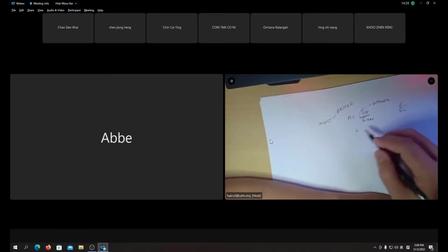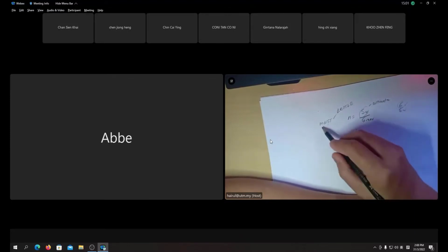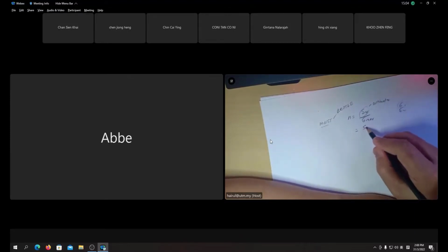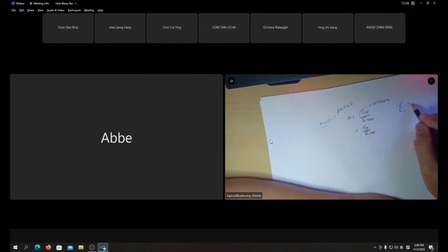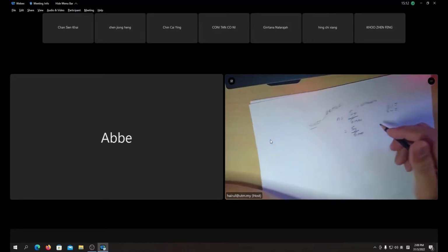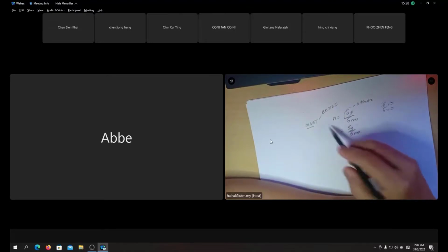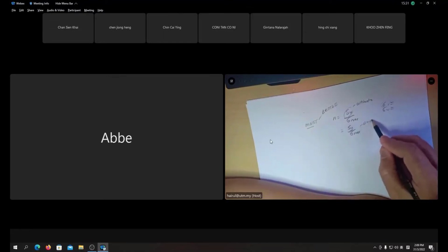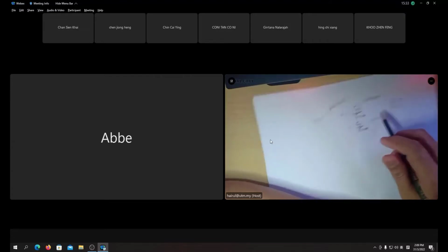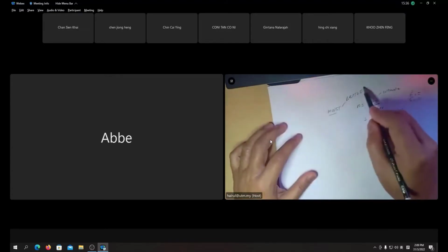But you can also go for ductile material with MNST, but you use SY instead of SU over your sigma max. Sigma max means you calculate sigma 1 and sigma 2 and take the biggest one, because sigma 2 is always compression, right? Negative. Sometimes the negative is bigger than the positive, then sigma 2 will be the max. Normally sigma 1 is bigger on the positive side. So that's why you can also go for ductile if you want. For ductile it's okay, but not that accurate. This one is actually for brittle, MNST.